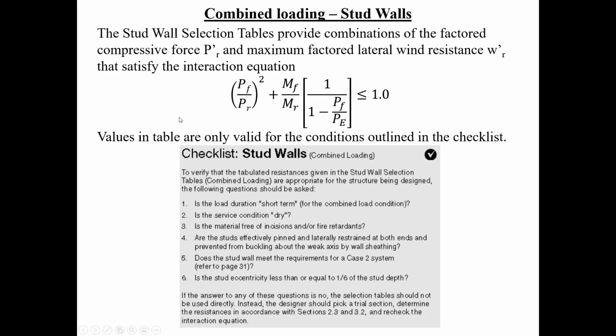And when you're designing a wall for a house, and the studs go, like I said, whatever you're supporting, as long as it goes over the whole width of the plate to transfer the load, you can consider it to be concentrically loaded. So the answer would be yes.